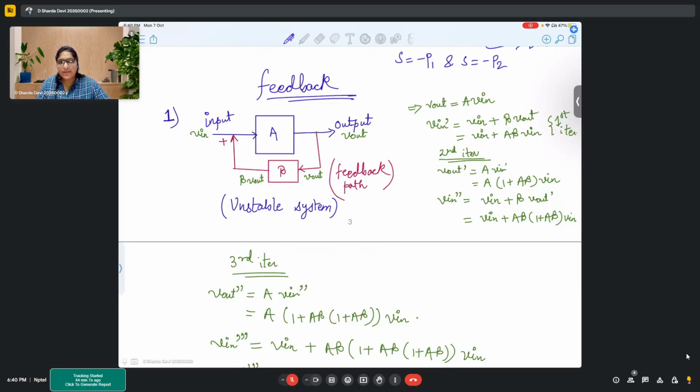because we'll talk about it most of the times. So, where you use feedbacks, right? You use feedbacks for amplifier circuits or oscillator circuits, or when you have basically the error correction and all that, controller circuits, control systems. So, basically, there you need the feedback. But that is definitely true that this thing will not go out of bound when you have A as well as beta less than 1.